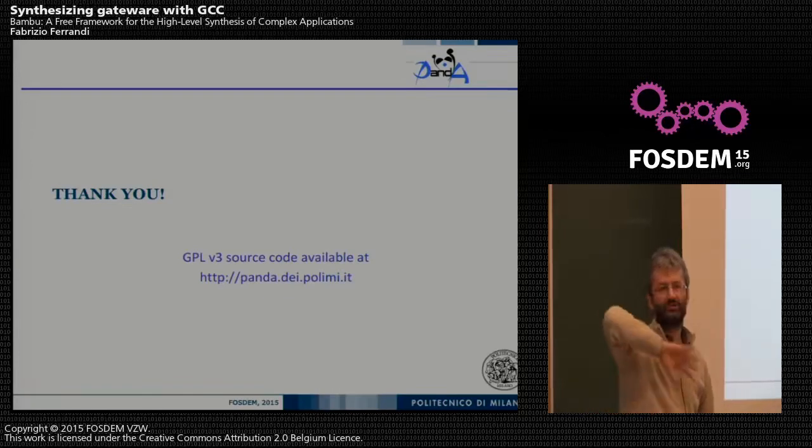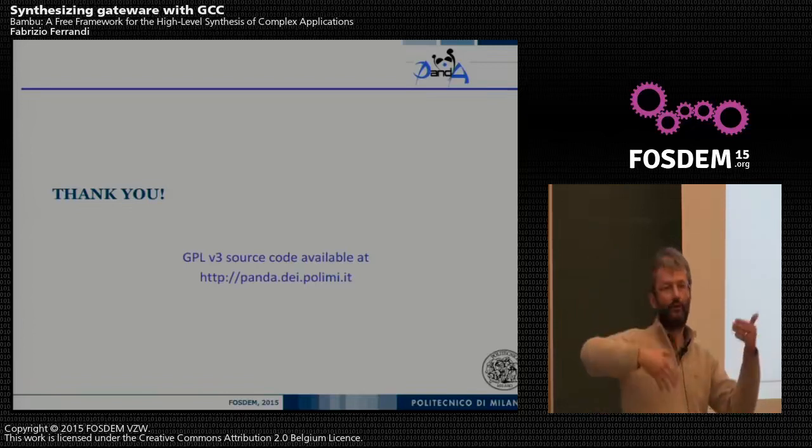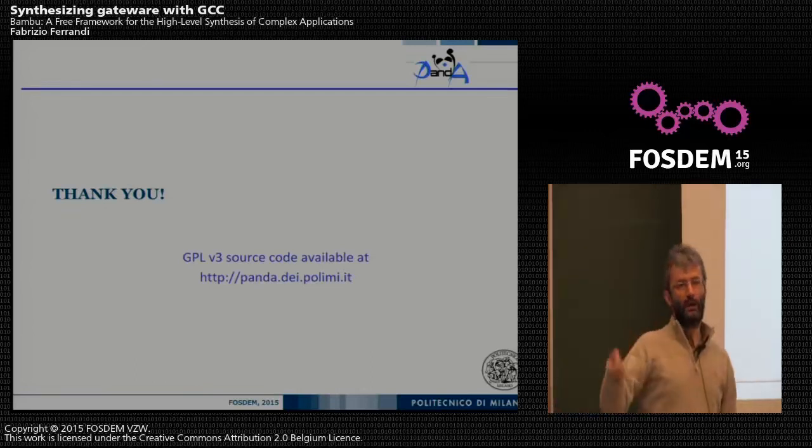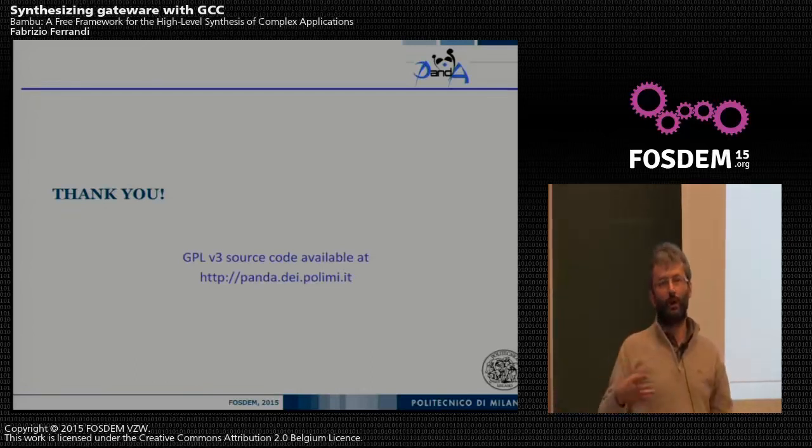Since we have a modular allocation, we use what GCC does in order to figure out the size of the element and so on and so forth. We have developed some units that are able to support aligned and non-aligned access to the memory, more or less as a processor does. So there is a bus where we put the address, the memory returns the data, and so on and so forth. That works and works pretty efficiently.